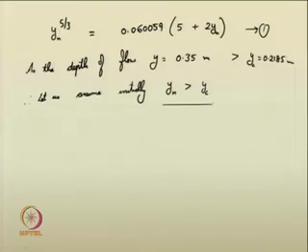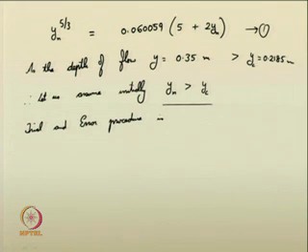You may not think that much of steep channels. So, if this is not true, then you can come back again and assume normal depth as less than critical depth, that is, it is a steep slope, and then you can start the computations. But let us consider the trial and error procedure.